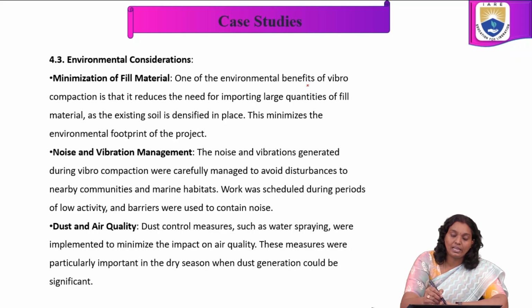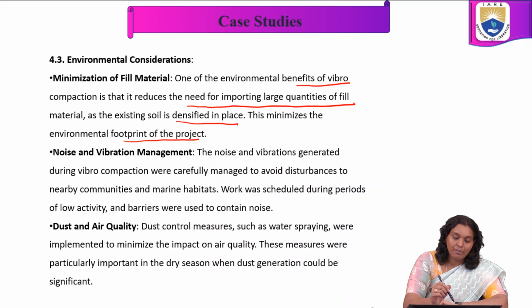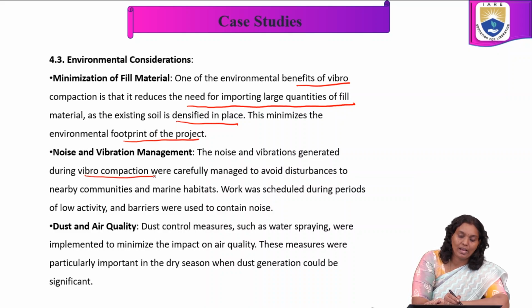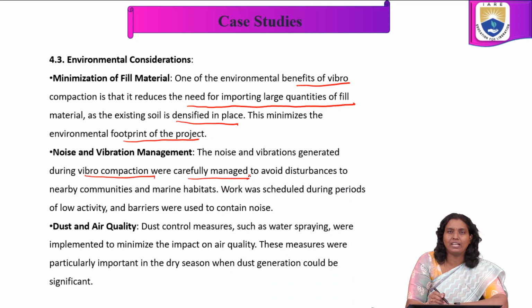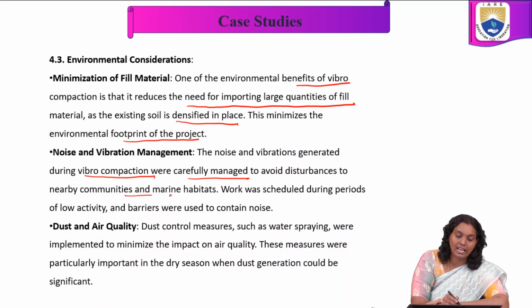One of the environmental benefits of vibro compaction is that it reduces the need for importing large quantities of fill material, as the existing soil is densified in place. This minimizes the environmental footprint of the process. Noise and vibration management: the noise and vibration generated during the vibro compaction were carefully managed to avoid disturbances to nearby communities and marine habitats. Work was scheduled during periods of low activity and barriers were used to contain noise.